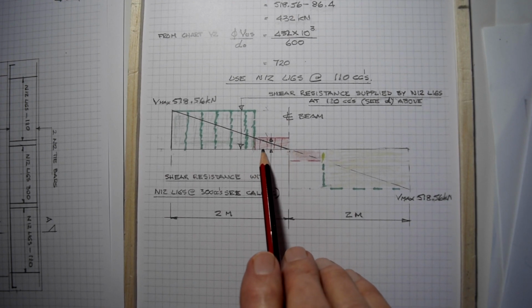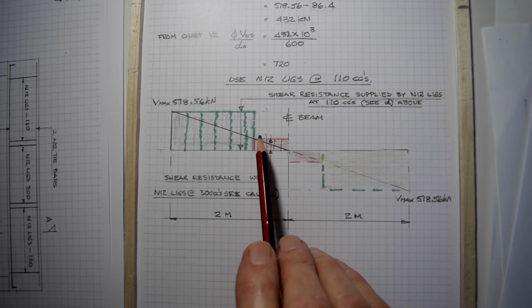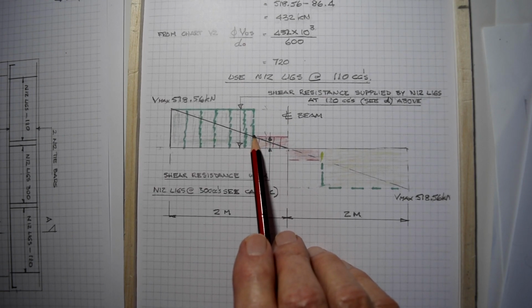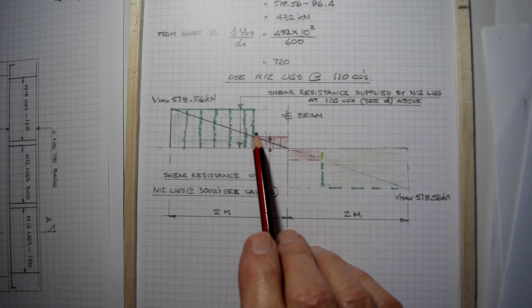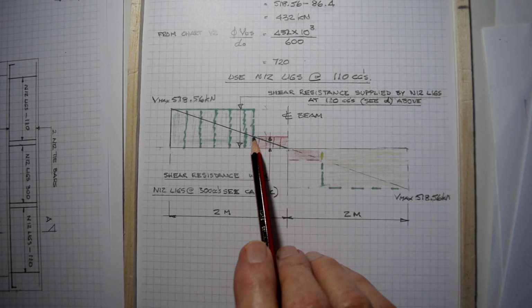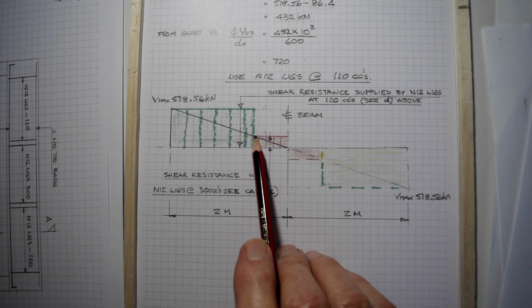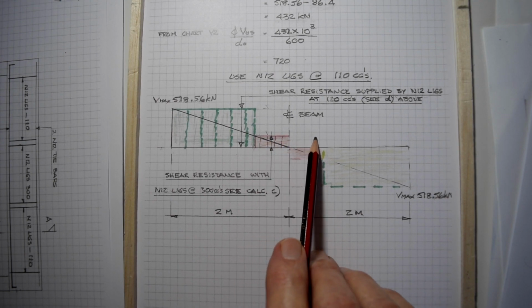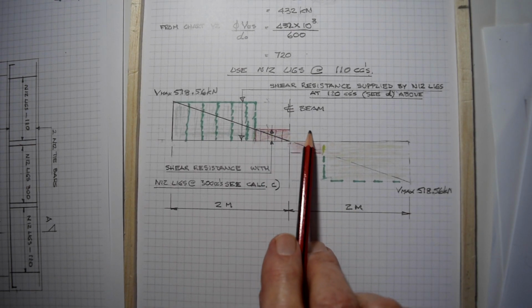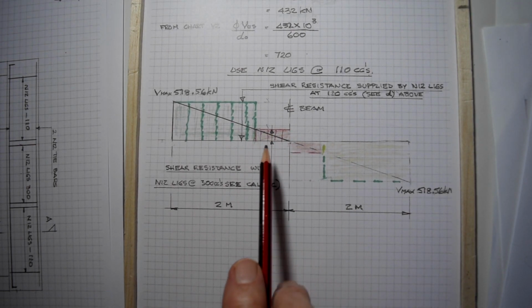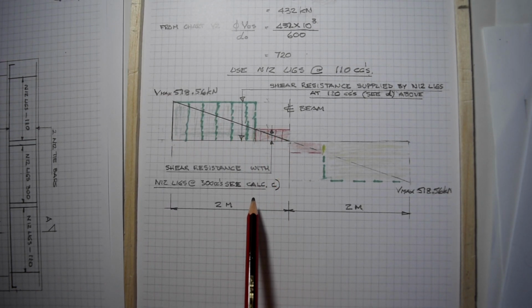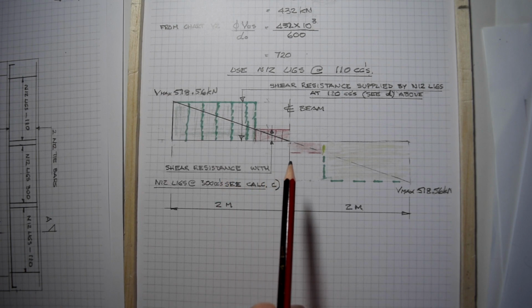In the centerpiece there, where the shear strength using just normal ligatures at 300 centers allows you to equal the actual shear force, we can actually put those right across in the central part of the beam in N12 ligs at 300 centers. So all I've done is do this. It's quite a useful sort of way of illustrating things.